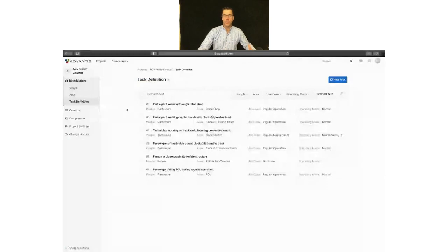Back to Linda's question, what is missing? It's that many risk assessments are not task-based. So what is the opposite? If it's not task-based, what is it then? Basically, they're looking at the physical build of the ride and saying, what if this breaks? What if this snaps? And that is simply a what-if, and at that point you end up in an FMEA, a failure mode and effect analysis. What if this contactor doesn't turn off? At that point, you're doing bottom up instead of top down. By going task based, you're automatically coming top down. And the task-based approach shows you risks to a greater extent than just an FMEA.